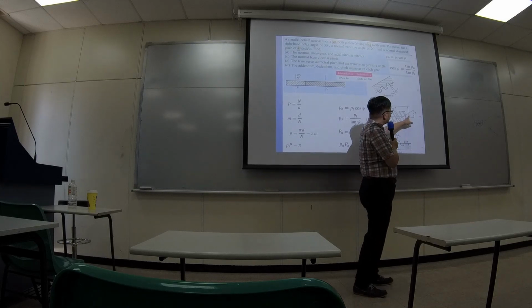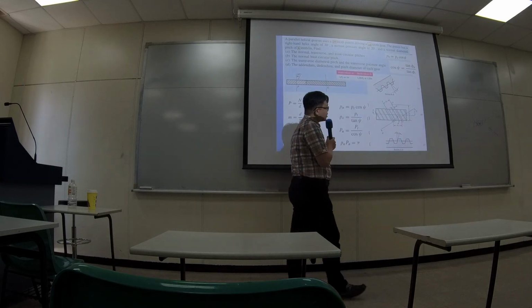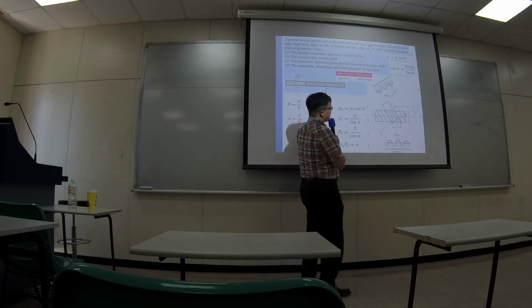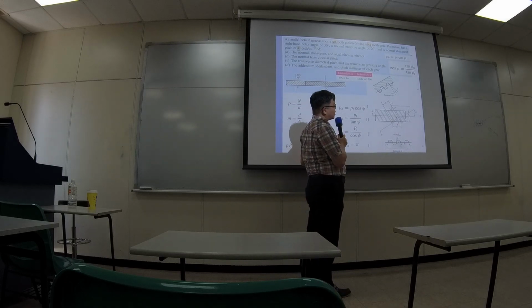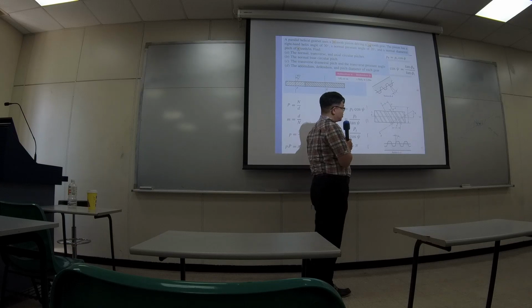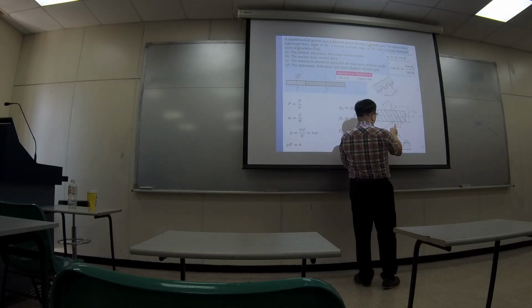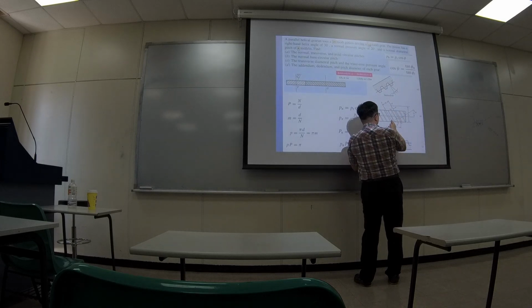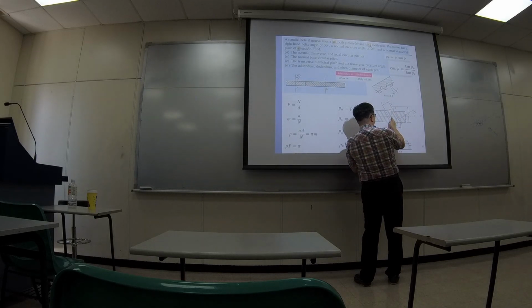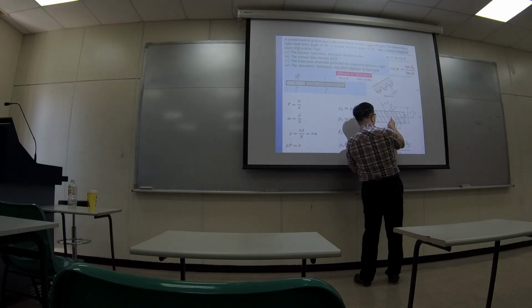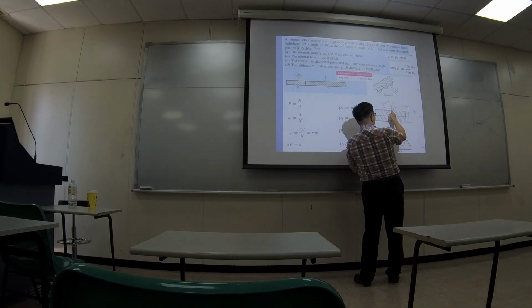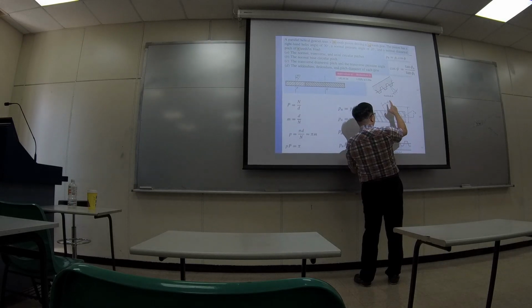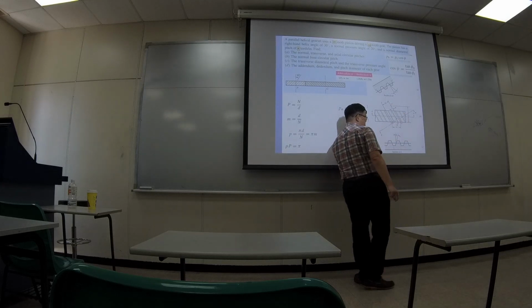How about Px? X represents the direction along the axis of the gear. So the axial pitch. How do you do it? Basically, you take a walk along the axis, and when you see a pitch, one edge of the teeth, going up and down, and then when you're about to go up again, that distance is Px.